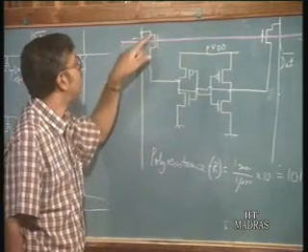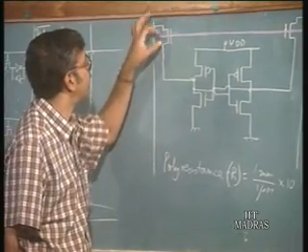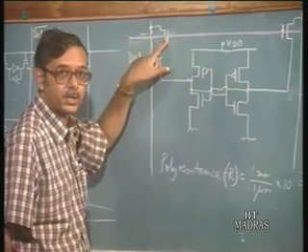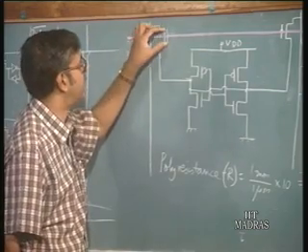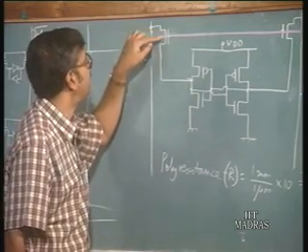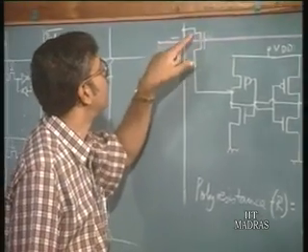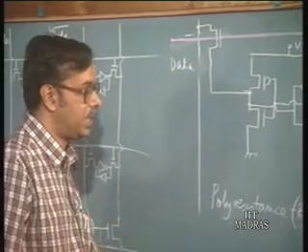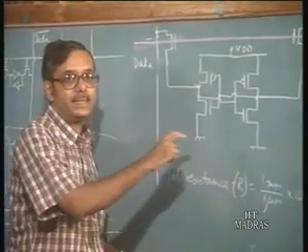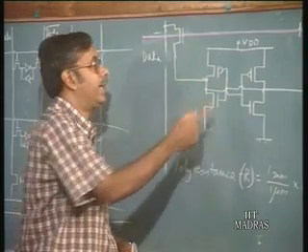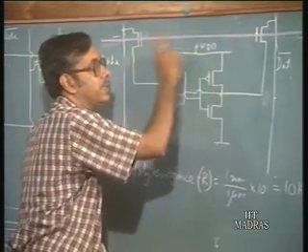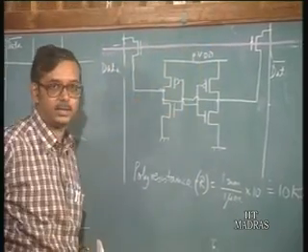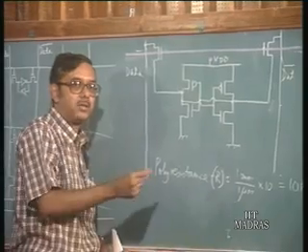Whereas, when it runs over the part that is the MOSFET, you have the gate capacitance, which is higher because the oxide thickness is less. So, partly this polyline runs over thinner oxide which forms the gate and partly over thicker oxide for the remainder of the line. If you have a 128 cell into 128 cell array, there will be 256 such transistors, because each cell has 2 select transistors, and each transistor is 1 micron by 1 micron.